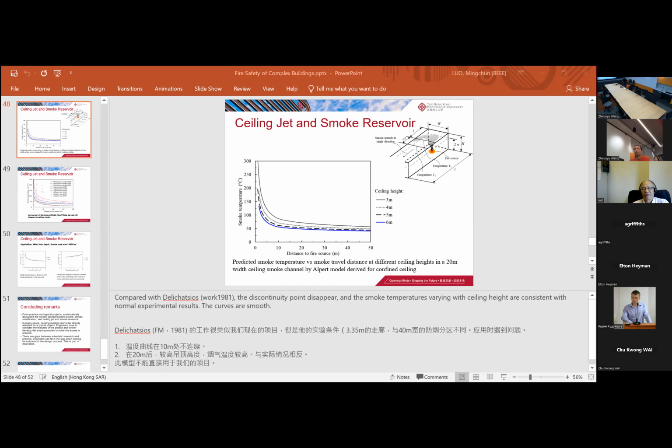The CFD model asks you for the heat release rate as an input to estimate or assess if your design is safe. Basically, if you have a smoke extraction system there, you need to specify the fan's extraction rate and the fire size, and then you do the number crunching with FDS, and it tells you this is not okay.